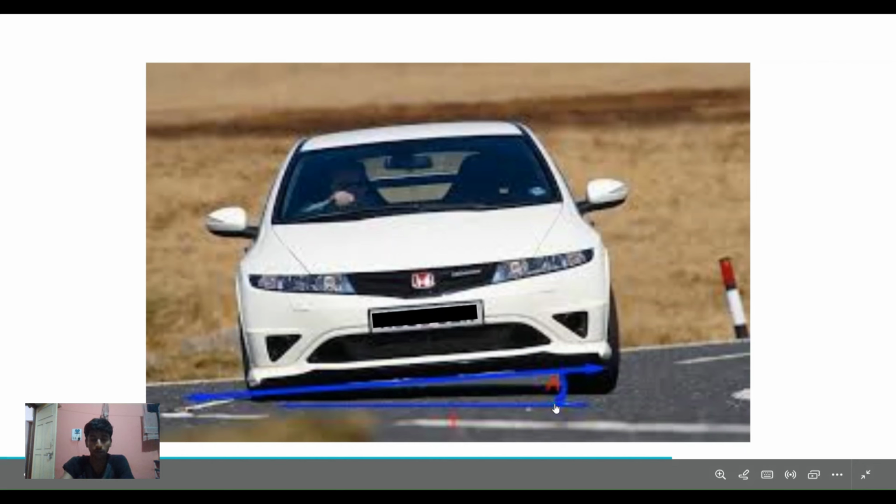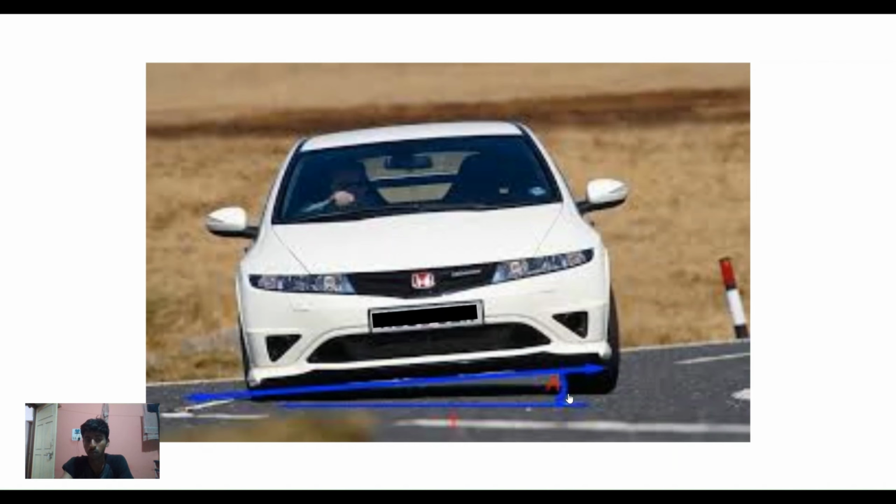When you have a larger track width, this angle goes smaller. That means there is better weight distribution on both inner and outer tires, which means the car is more stable and under control. Rather than having the car tip over, having a wider track width will always help achieve that much required control when you're going at top speeds or doing very tight maneuvers. Always keep track width wide. That's what helps you.